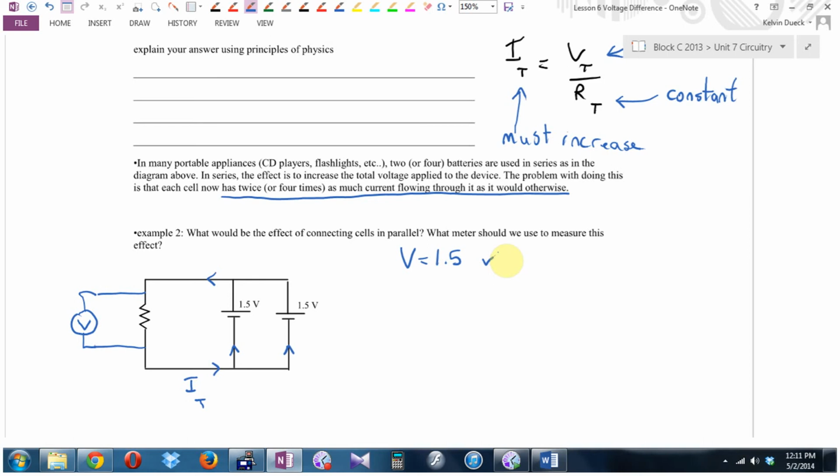In your fancy schmancy graphing calculators, I know a few of you have them, for example, I noticed that this is 4 batteries in parallel. This lasts quite a while. In fact, right now I think I'm on to 2 years with this batch. Okay? This only needs about 1.5 volts, but I can share the load and I can get the batteries to last longer. You also will see sometimes in some remote controls a combination. You'll see 2 batteries in series, 2 more batteries in series, so that system needs 3 volts, but if we just did it that way, it would run dry so fast, we put a second set in there so that your batteries last a bit longer. Your remote controls, almost all of them could run off of just one of these, but they would only run for about a week or so.